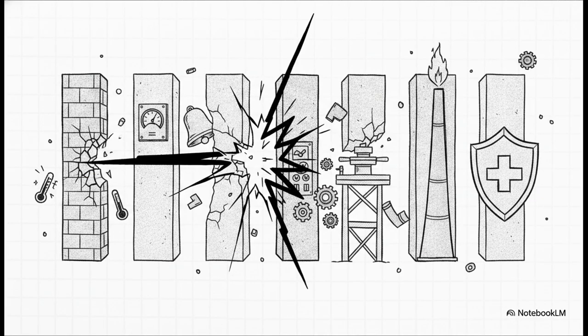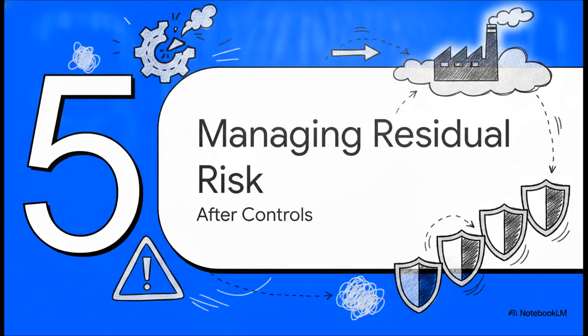Safety engineers use this tool called a layer of protection analysis, and when you apply that to Bhopal, we see that literally every single layer of protection failed. The fundamental process design? Failed. The temperature controls? Disabled. The critical alarms? Entirely failed to warn anyone in time. There was absolutely zero automated safety system in place. The relief system, the flare, the emergency response? All of them failed. This demonstrates exactly what happens when an organization completely ignores proper risk evaluation and just strips away its layered defenses. Finally, let's look at Section 5, Managing Residual Risk.